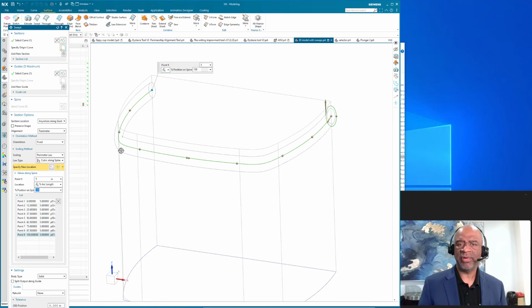And the list is great because now I can click on any of those points and I can assign the correct dimensions. So for example, I click on point number 1, and right here I type in the variable a, I put a space after it, and then I click on point 2, and this one is b space, enter.